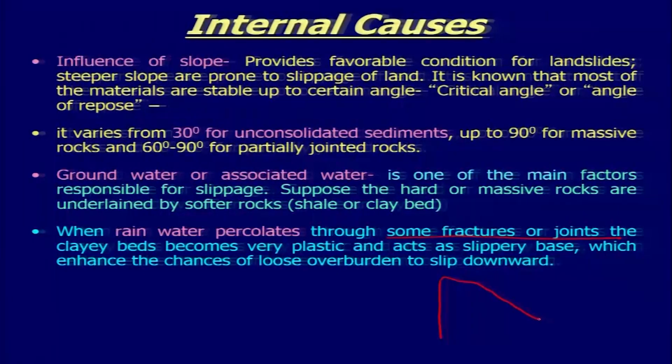If you are having this mass here and then this is a clay bed, even if the overlying rock is harder, you are having this plane which is likely to slip, because as soon as the water gets in, this will change its property and act as a plastic and slippery base, which enhances the chances of loose overburden or even the harder rocks sitting on top of it to slip down.